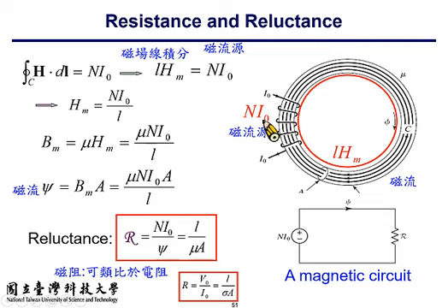And the conductivity can be compared with what? Permeability in the magnetic circuit. And you can draw the magnetic circuit of this one like this. So that's probably the simplest magnetic circuit. You have the magnetic flux source Ni sub 0, and here is the reluctance R, and the thing that goes around in the magnetic circuit is the magnetic flux phi. All right.